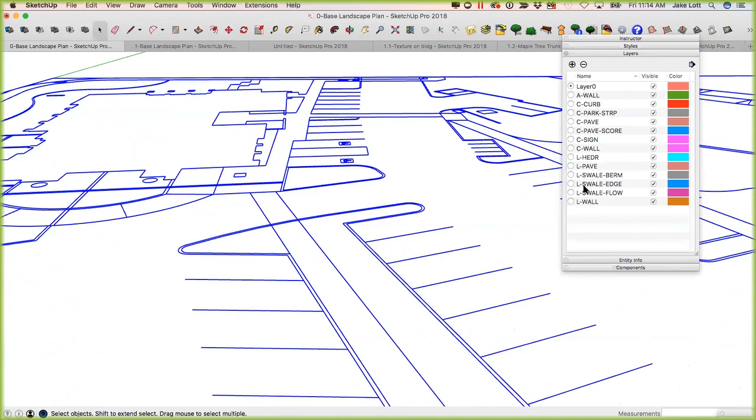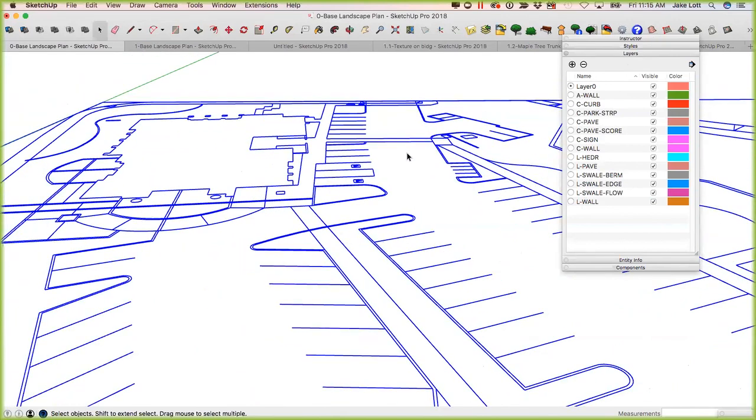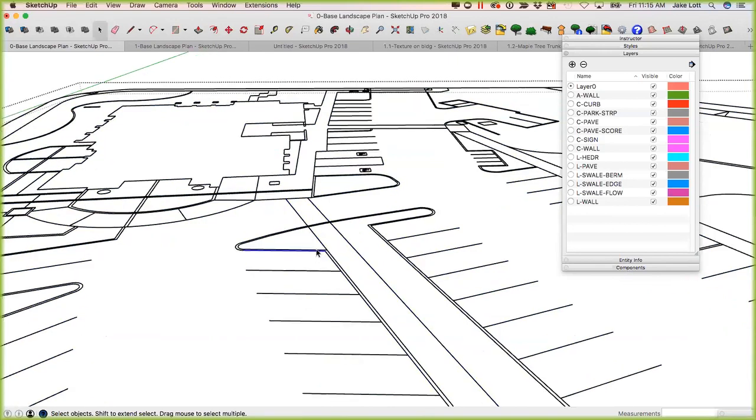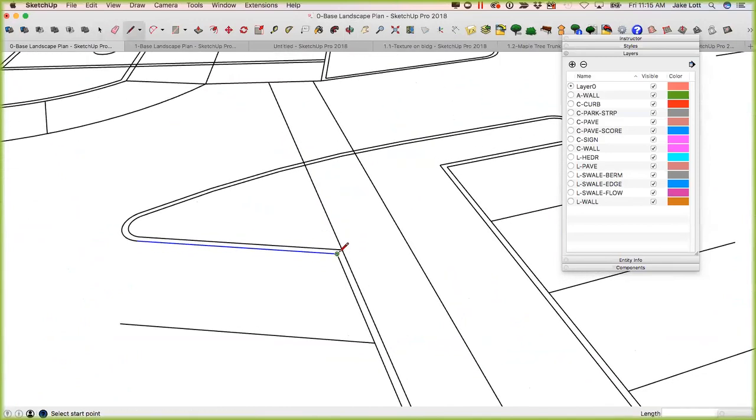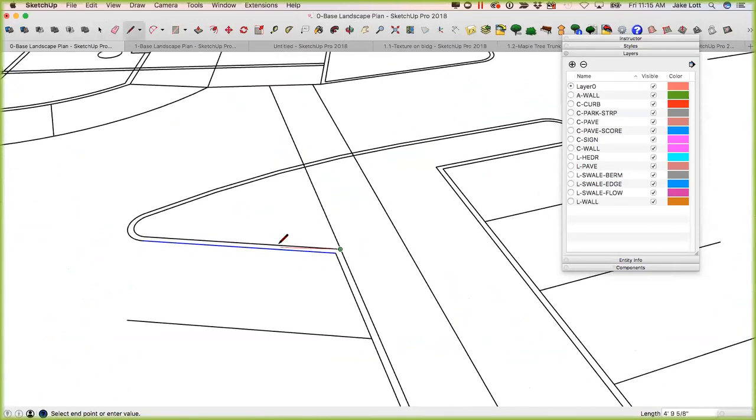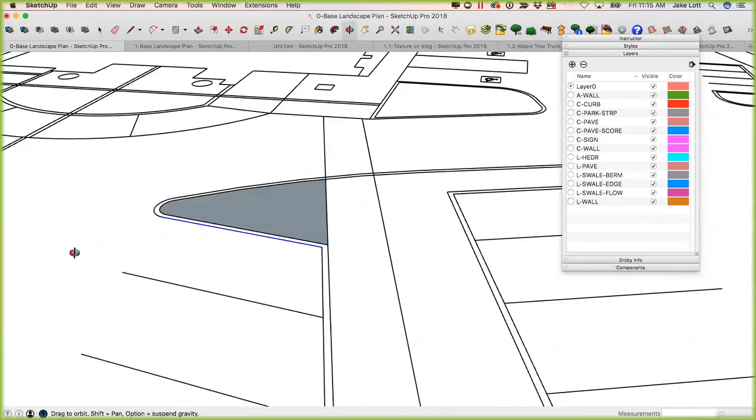And whether it's a curse or a blessing, that's the beauty of SketchUp. You can actually draw and cut into lines and section them off, but you might think that's how things are separated by layers, so that you can do things kind of on their own layers and have it work that way. Layers are actually a little bit misleading. Layers are actually used to manage geometry visibility. That is it. So even if you have line work on certain layers, you can draw and still intersect and kind of mess up that stuff.